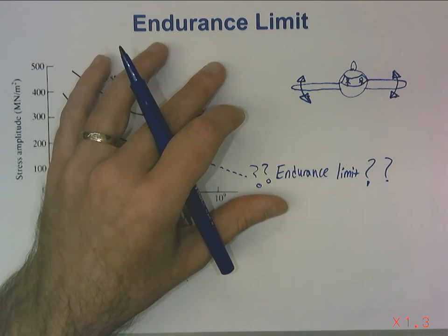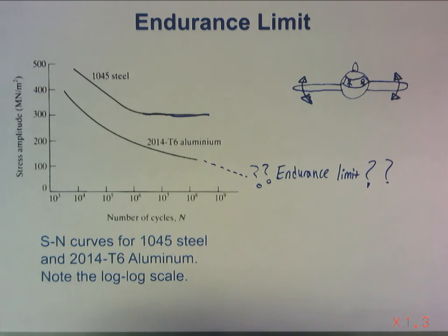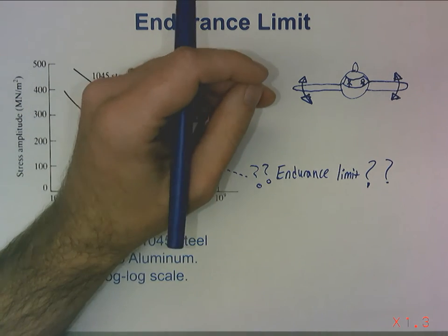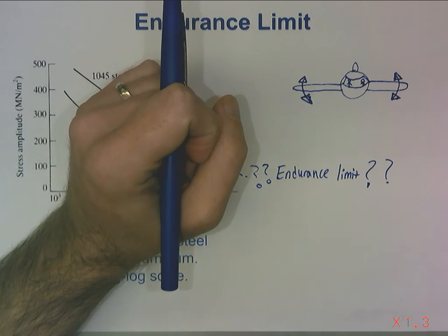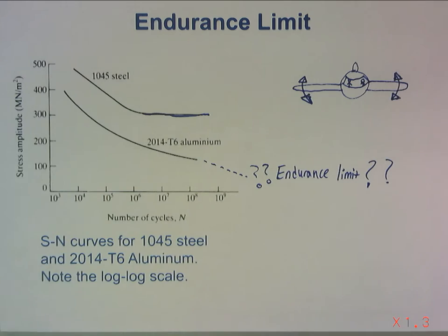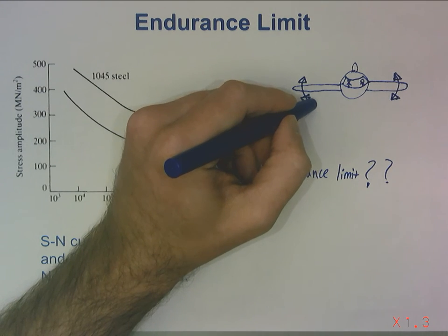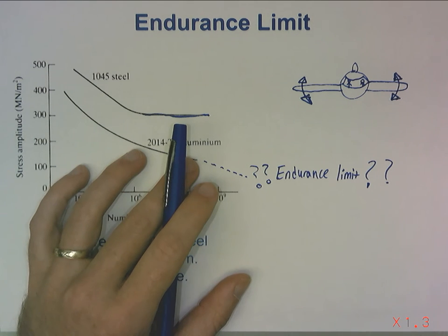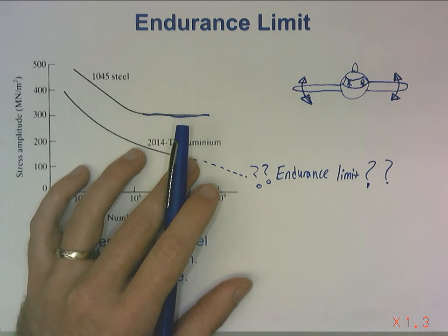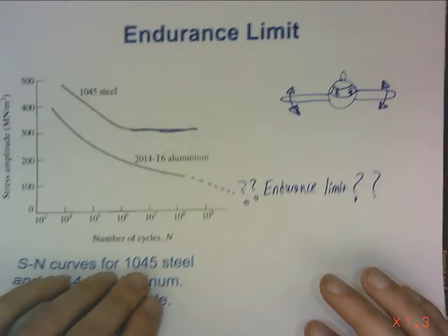And he just loved to watch the general people around him start freaking out as he explained crack growth and how all the airplane wings have fatigue cracks in them, and they're all going to fall off someday if we don't recycle the planes. We take these things out of service way before they should fatigue fail. At least we're supposed to. But it's true. All of our aluminum parts that start experiencing cyclic loading are going to have fatigue cracks. So, just part of the mechanical design that we have to worry about.